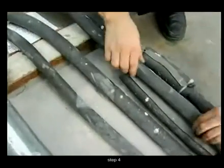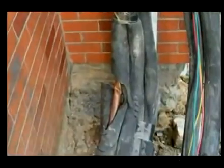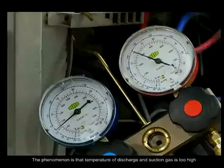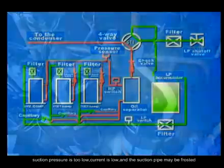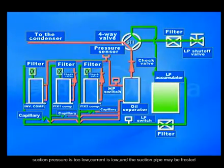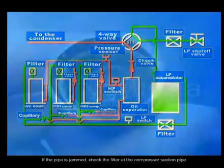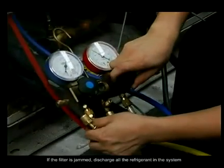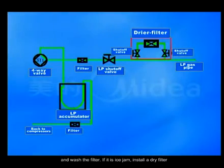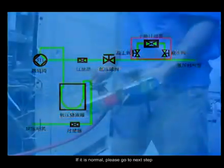Step 4. Check if the pipes of the low pressure side are jammed or deformed. The phenomenon is that the temperature of discharge and suction gas is too high, suction pressure is too low, current is low, and the suction pipe may be frosted. If the pipe is jammed, check the filter at the compressor suction pipe. If the filter is jammed, discharge all the refrigerant in the system and wash the filter. If it is an ice jam, install a dry filter. If it is normal, please go to the next step.